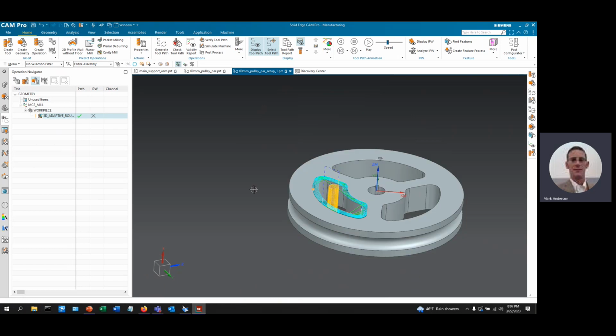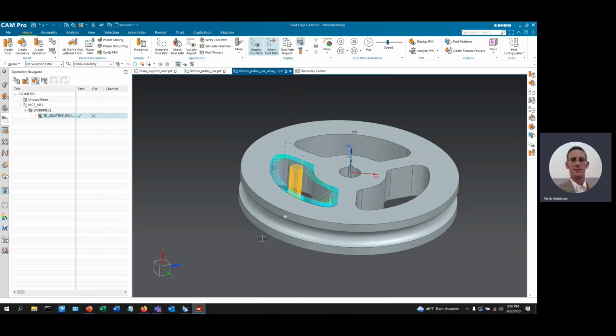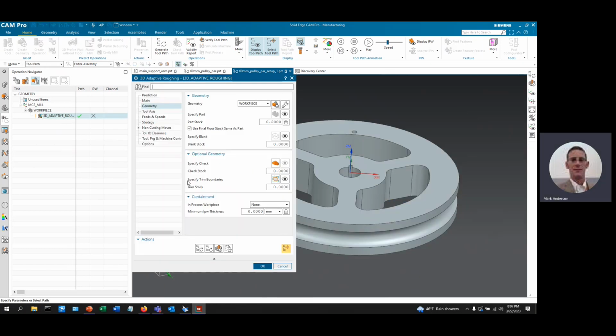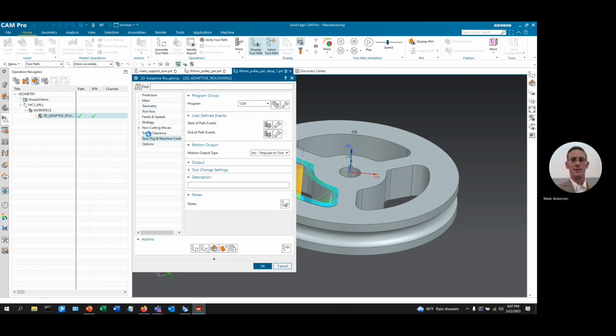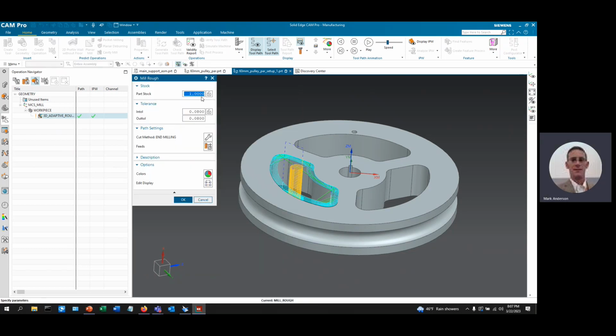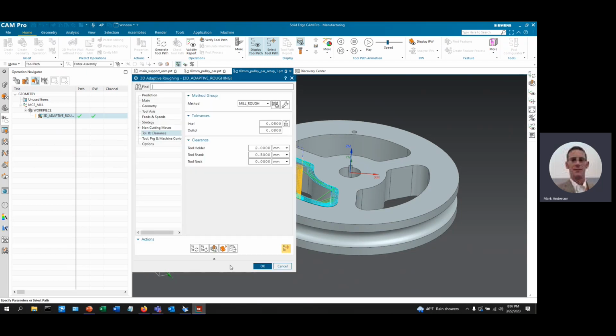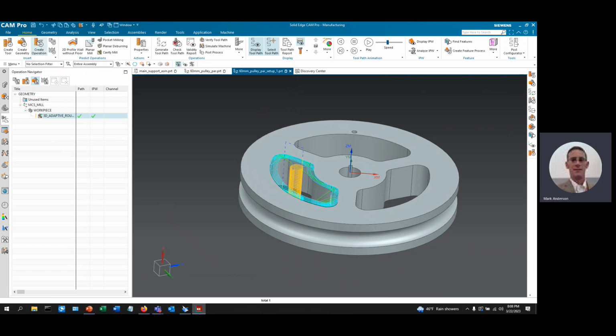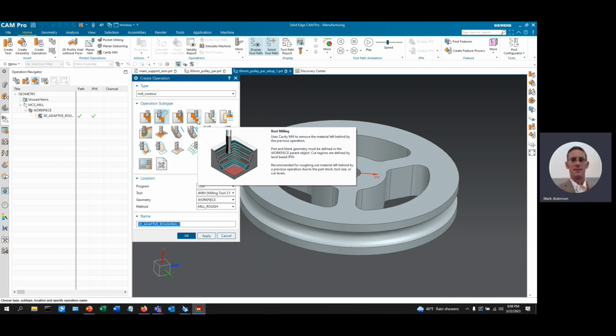So that is our very high-speed material removal. Now, this is in a roughing strategy. So if it has material left over, mill rough, and it has 1 millimeter. So now one of our next operations that we could use would be our patented rest milling.